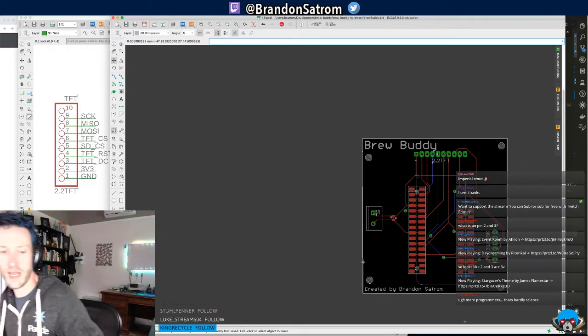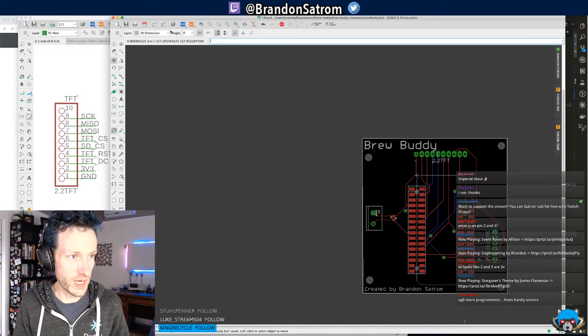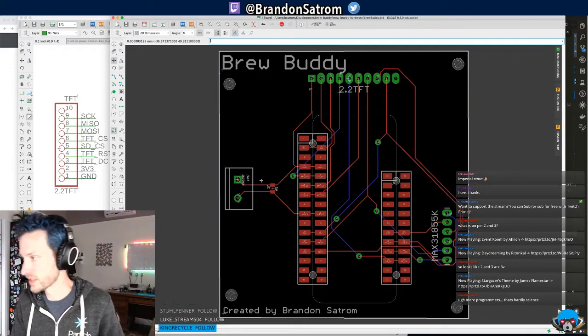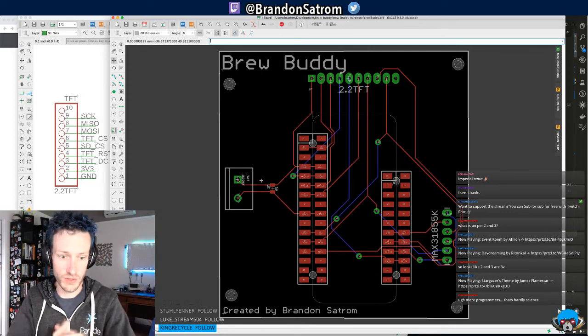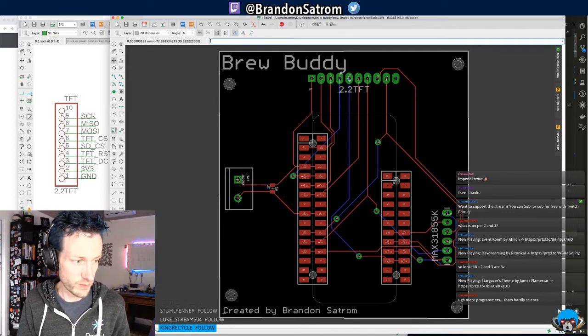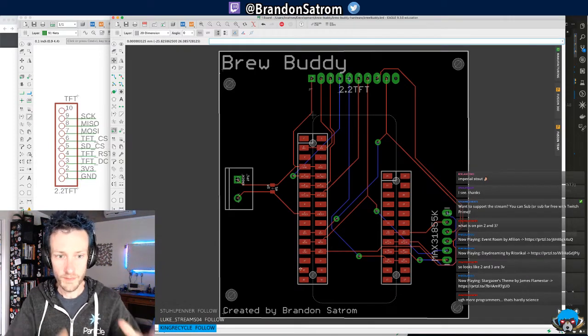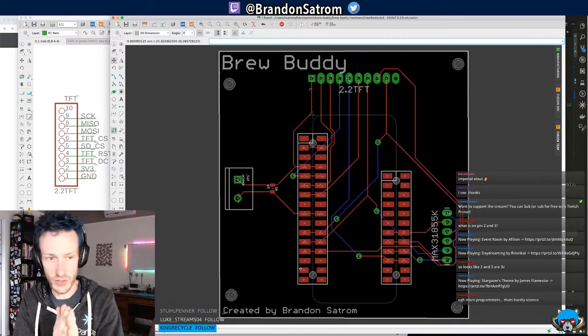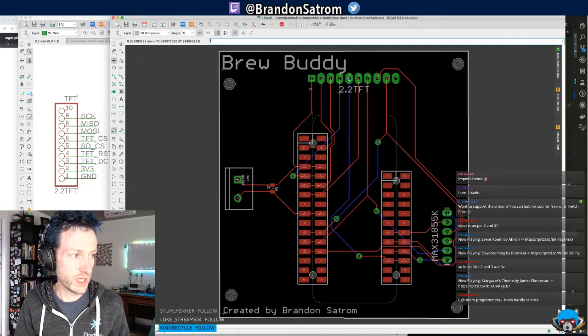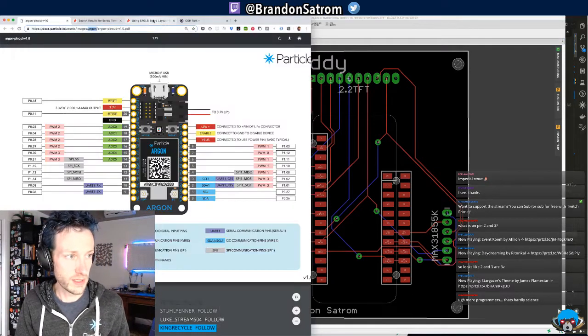So now that I have this in sort of a nice, let me zoom in here so y'all can see it. This is our board. This is what we've managed to craft and create over the course of the last couple of hours. I can run my design rule check on this to see no boxes come up. Everything looks good. So this is actually ready for me to order, to go ahead and make happen.